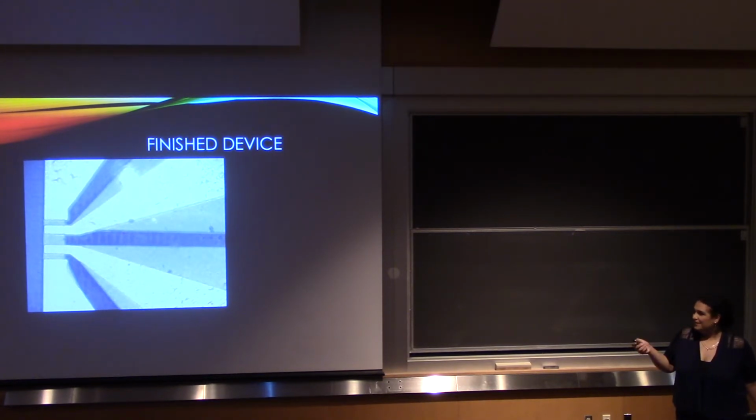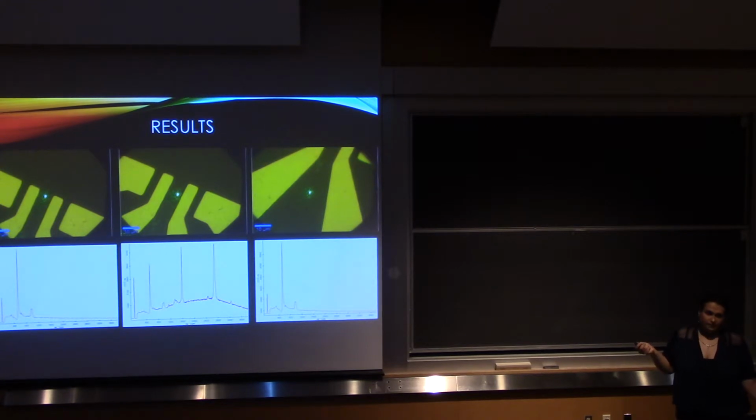And so as you see, the graphene is where it should be, as I talked about earlier, and the metal contacts are there. And to make sure that what we see is exactly what we want, we did Raman spectroscopy, and we measured our graphene in 3 different sections of the device. First, I need to tell you about the graphene peaks. When you put graphene in the Raman spectroscopy, it gives you two distinct peaks, one at approximately 1600 and the other at, I believe, 2700.